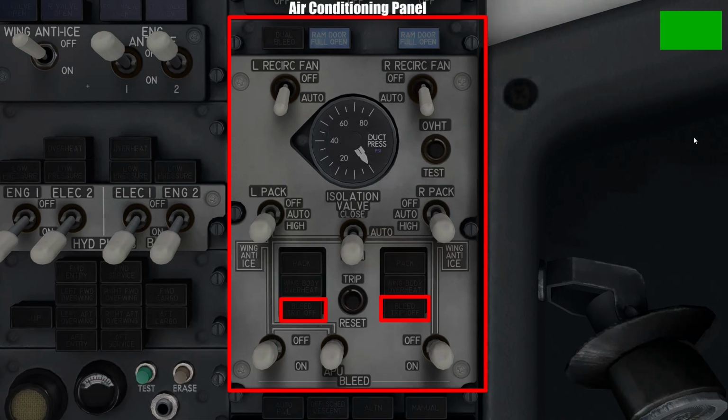Finally, the last light down here is a bleed trip off light, which illuminates when the bleed air being supplied to the pack is too hot, thereby leading to an increase in heat in the pack system, causing it to shut off. When pilots identify this problem, they can either choose to turn off the pack systems and allow them to cool down, or if it's only one pack that's malfunctioning, they can turn the isolation valve to on and turn the other pack system to high speed to take over the responsibility of the malfunctioned pack system.